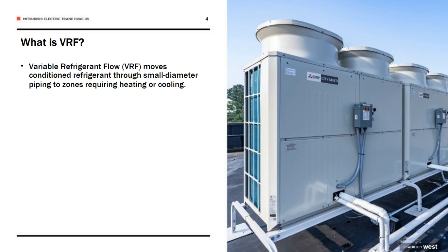In addition, VRF provides the ultimate personalized comfort experience for a building's occupants. Each space or zone requiring conditioning will have their own network of indoor units. This network of indoor units is controlled from within the space, providing the occupant with the ability to personalize their comfort. Some systems can even cool some areas of a building while heating others from the exact same system. This leads to happier tenants and fewer comfort control complaints for building owners and facility managers.